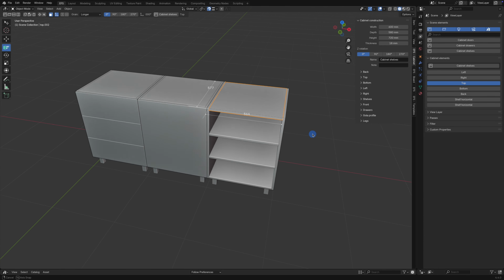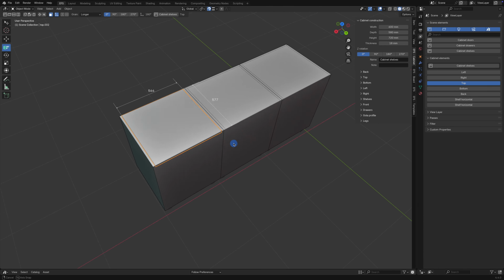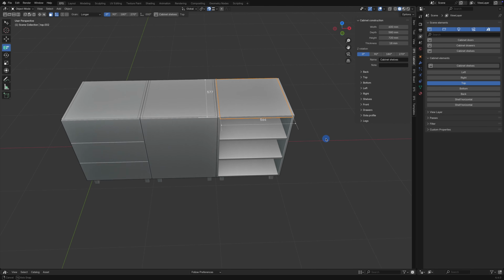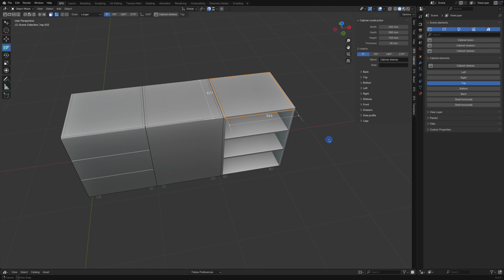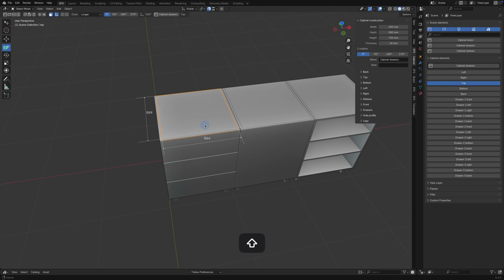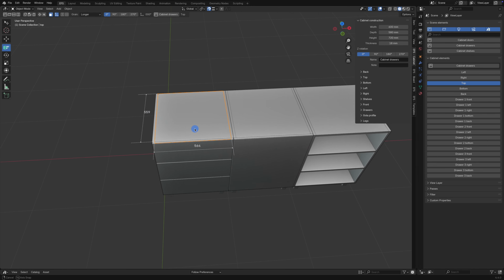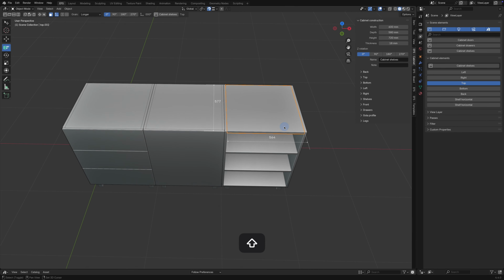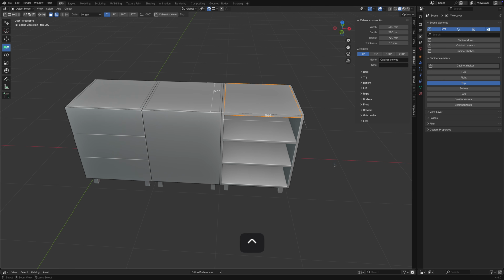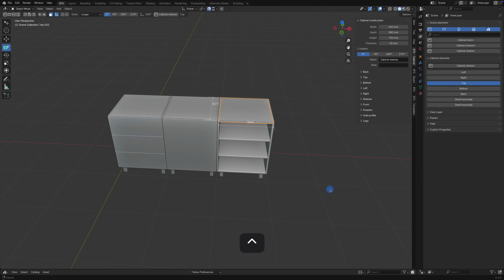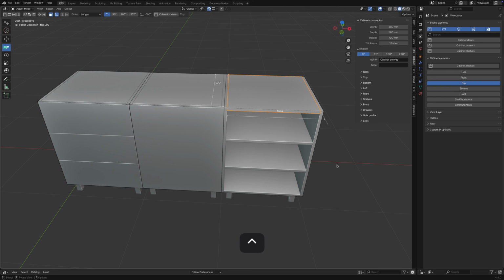To better examine your furniture from different angles, press and hold the middle mouse button or wheel and drag to rotate your view. An important detail to remember is that rotation always occurs around the active object, the one highlighted with an orange dot. When you select a different object as active, your view rotation will center around that object instead. Control your view distance by using the mouse wheel to zoom in and out, or click the zoom icon and drag while holding the button. You can also hold Control and drag with middle mouse press for fine control.